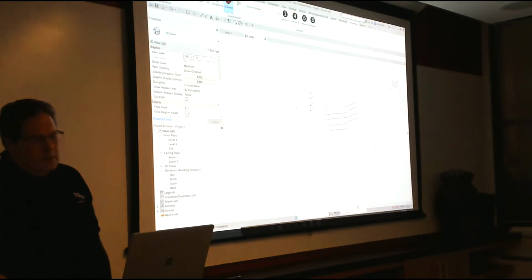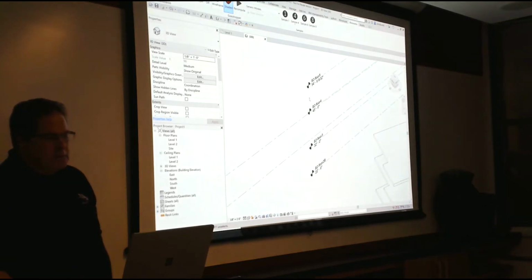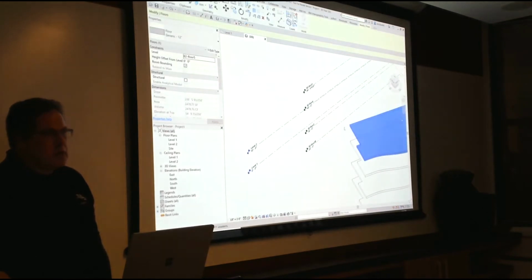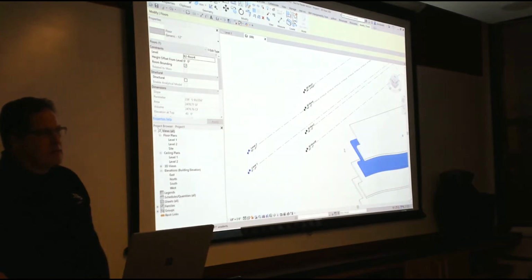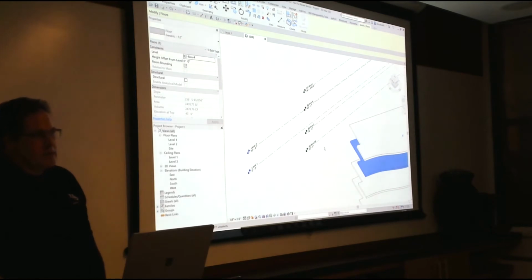All right? And so if you're over here, you're going to see in Revit, I have my levels named properly with my system floors hosted on that level. Now, if somebody downstream gets this in just Revit, nobody will know that it was created in Rhino. It looks like a regular, everyday system floor, as if you created it in Revit in the first place. Hosted in the right place, by the way.